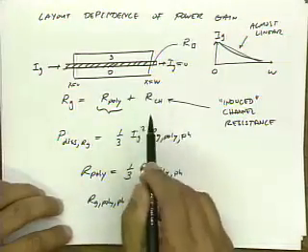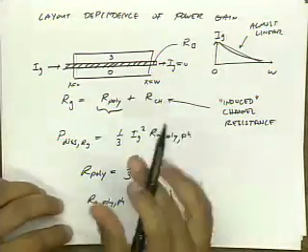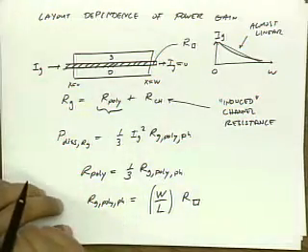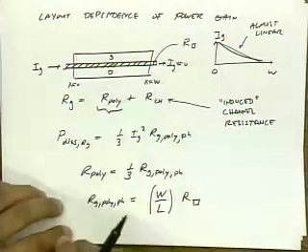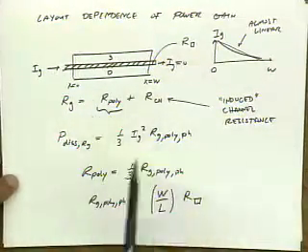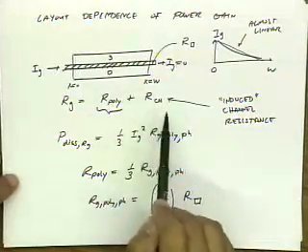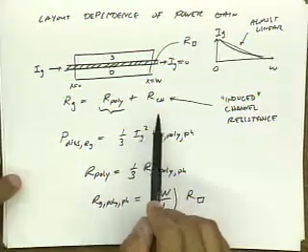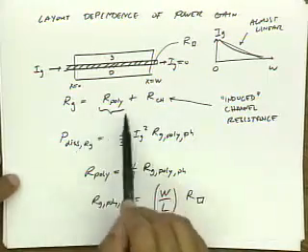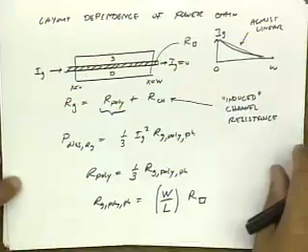Intuitively, you would say that this should be proportional to the channel resistance. So if I go in there and look at VDS sat divided by IDS, that's roughly the channel resistance, and so this term should be proportional to that channel resistance. We'll come back to that. Let's focus on this term. So because this term is bias dependent, I can always bias my device to have a higher and higher current and lower channel resistance, and so I can eventually be dominated by just this term here. And this term, of course, does not depend on bias.